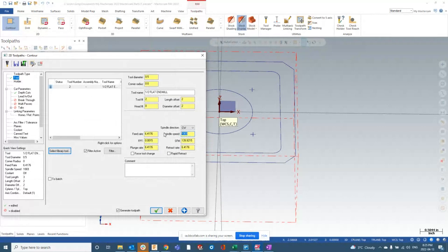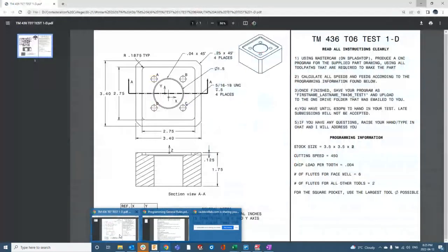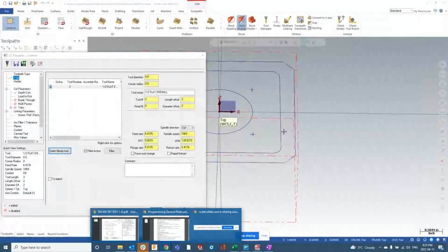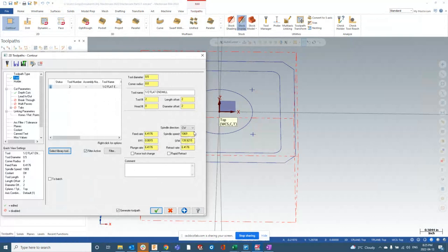They work really well. I'm going to take my cutting speed, which was in this case, again, 450 times 4 divided by 0.5. I get 3,600. That's probably pretty conservative for a 1/2 inch end mill, but that's fine. 3,600 times 2, because I said 2 flutes, times 0.002. I get 14.4. Pretty conservative. You guys will have different numbers. I've come up with a better way of teaching my speeds and feeds.